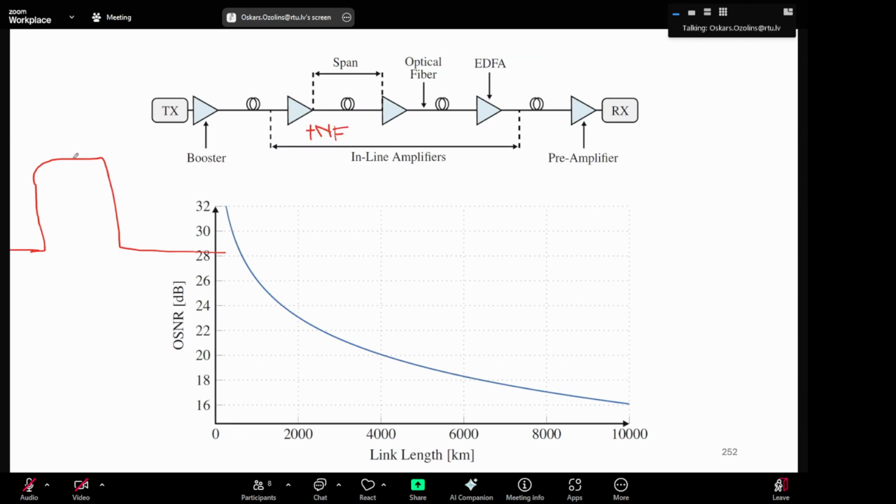When you measure the optical signal to noise ratio, you want to measure the integral power here. So you measure one integral power here, and then you need to estimate the noise level here. Then you need to convert it to the same resolution, and then you know what the noise level is and what signal plus noise is, and you can calculate the optical signal to noise ratio.